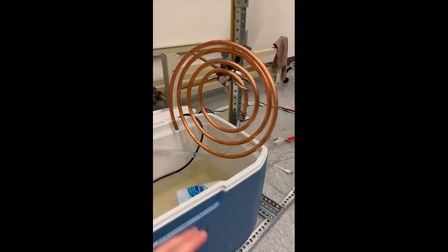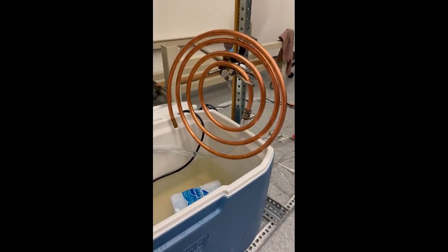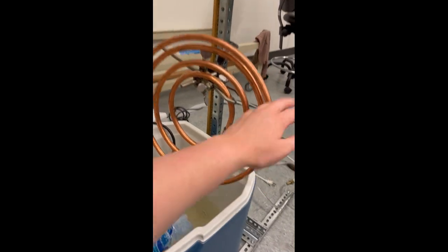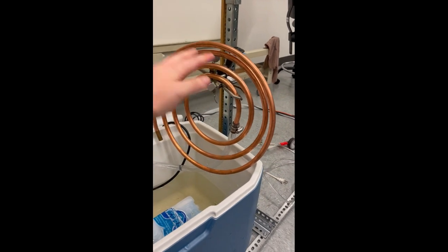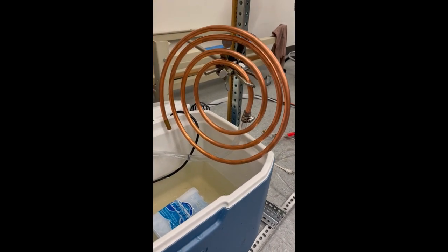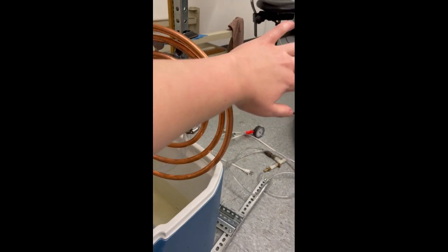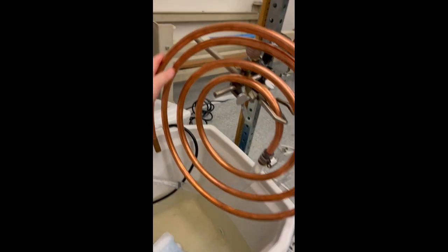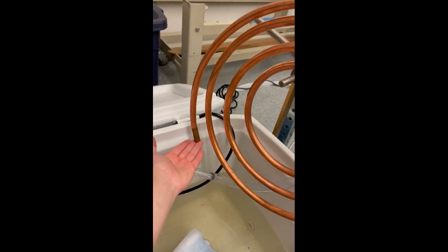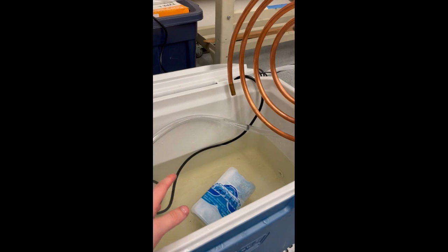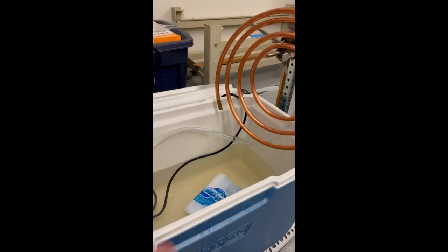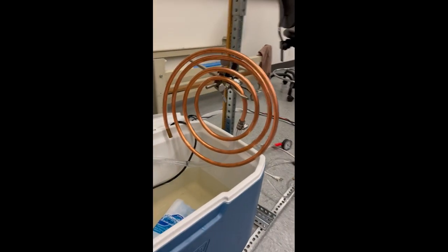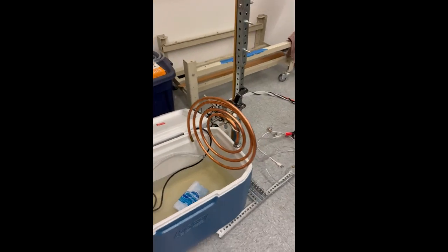So copper has been selected because it has a really high thermal conductivity as well as electrical conductivity. As the cold water circulates through all of these coils, it's in contact with the surrounding air environment, and so heat will leave from the air through the pipes into the water, which will, as it continues to circle out through here, come back out through this end of the pipe and back into the ice bath where it would cool back down to around freezing. And the cycle continues as we continue pumping more water through, and heat continues to leave the surrounding areas. So let's turn it on and see it in action.